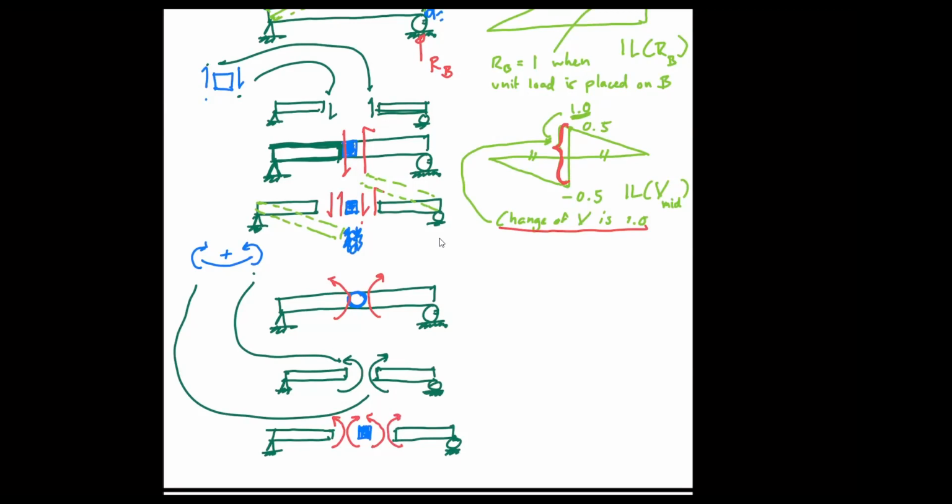So now, when you apply the moment and you no longer have the restraint because you add the hinge, it will move freely, resulting in this segment going up like that. It's like you're trying to open the door, you know, and this is the hinge of your door. It goes up like that. Okay.